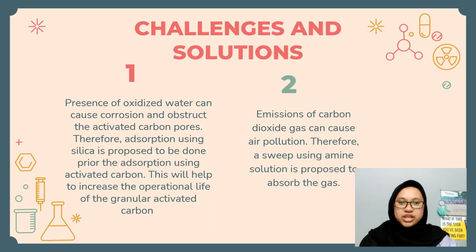For the challenges and solutions, we figured out that the presence of oxidized water can block the pores of activated carbon. Therefore, we propose to have the adsorption using silica before the activated carbon to remove water. Secondly, we all know emissions of carbon dioxide to the environment will cause air pollution. Therefore, a sweep using amine solution is proposed to absorb the acidic gases to reduce its environmental effects.